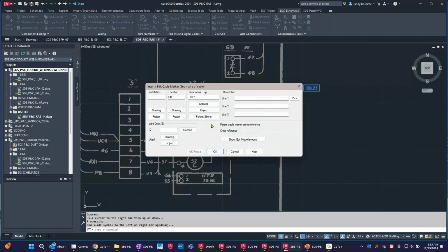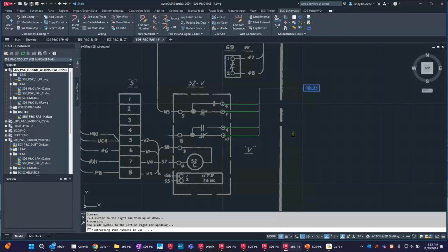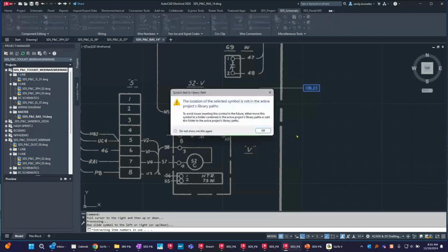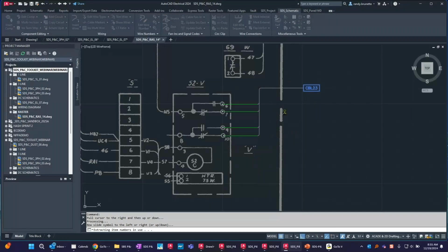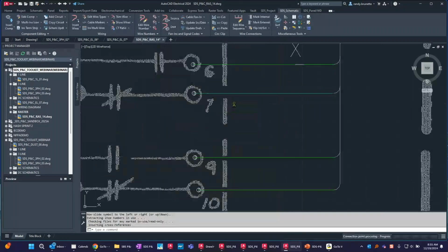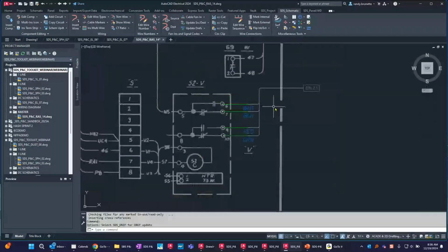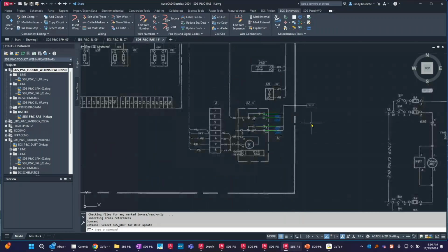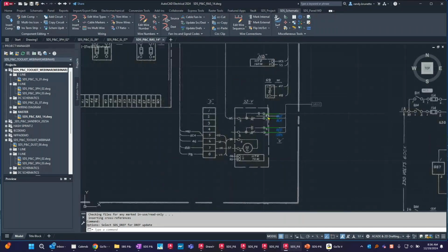Once again, you can see it's automatically placing in source, or in this case, the destination markers. It's placing in, drew the wires that were coming out from the components, switched those automatically to the multi-wire layer and placed in my component. Quick, easy steps to drawing cables between components in our drawings. Now, I use tie links to draw the cables in, but really the tie links were just providing the connection points for the cable that we're working on.